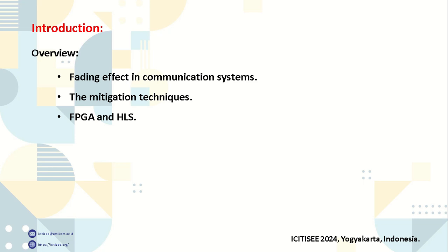Traditionally, FPGAs are programmed using HDL, or Hardware Description Language. However, in this implementation we utilize a high-level synthesis-based approach, or HLS, which uses high-level languages like C and C++ to implement the required hardware. It offers higher flexibility and fast development time.